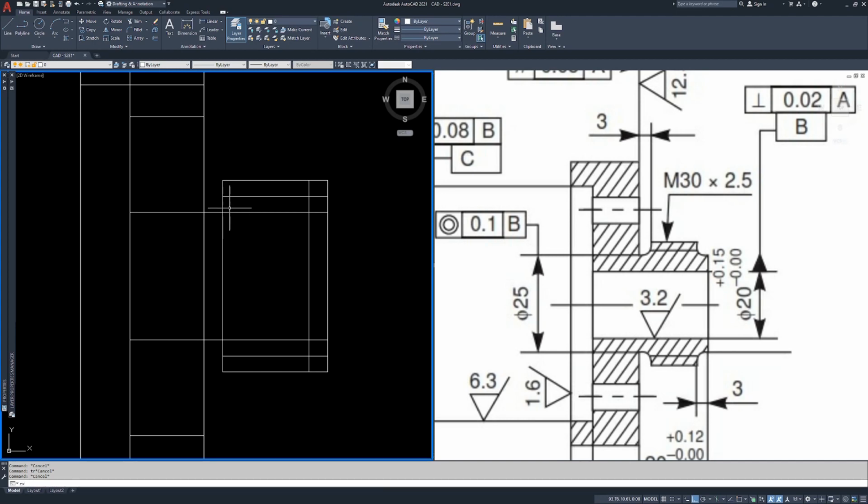That lets us use the extend command actually. EX, right click, pick this edge here, right click again, extend these two lines in because this needs a thickness here that's thicker than this 20-unit opening. So this 20-unit opening here is from this point to this point. We still need this fat part on the top and the bottom, which is in here and in here. So we're going to trim again. I'm just going to window select the vertical and horizontal, and I'm going to trim out the outside corners. Okay, so we have our general shape here.